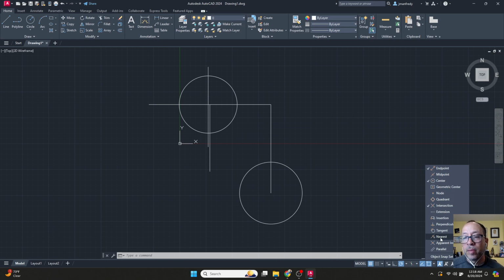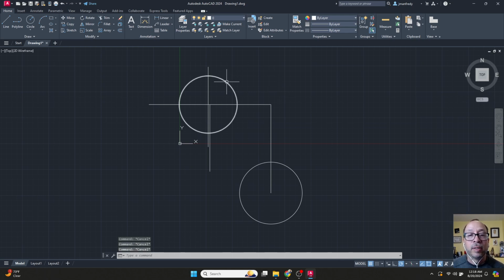is one that basically lets you snap anywhere near an object. So let's say I want to snap to the circle perfectly near where my mouse is. Near snap is not currently active. If I type L and I want somewhere to be near here, you see it's launching the center. It thinks I want the center. Or if I hover over here, I think it wants the end or the intersection. But I want the near snap. And so it might launch a different location that I'm not really interested in right now.